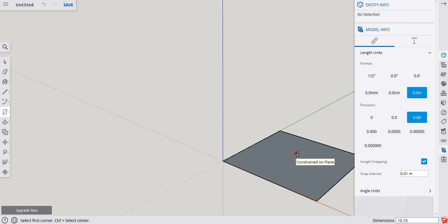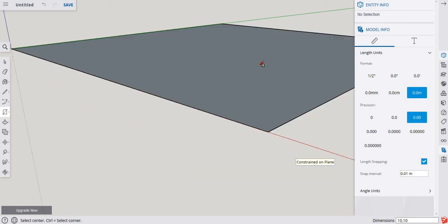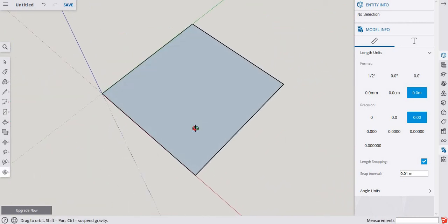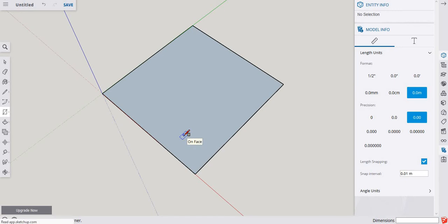Now Control Shift E will do what we call zoom extents. Kind of zooms in on the entire thing. You can see it's a perfect square. If you don't believe it, hit T for the tape measure tool, and you can move from one end to the other. Look at the bottom right, and it says 10 meters, or it shows it on the screen.